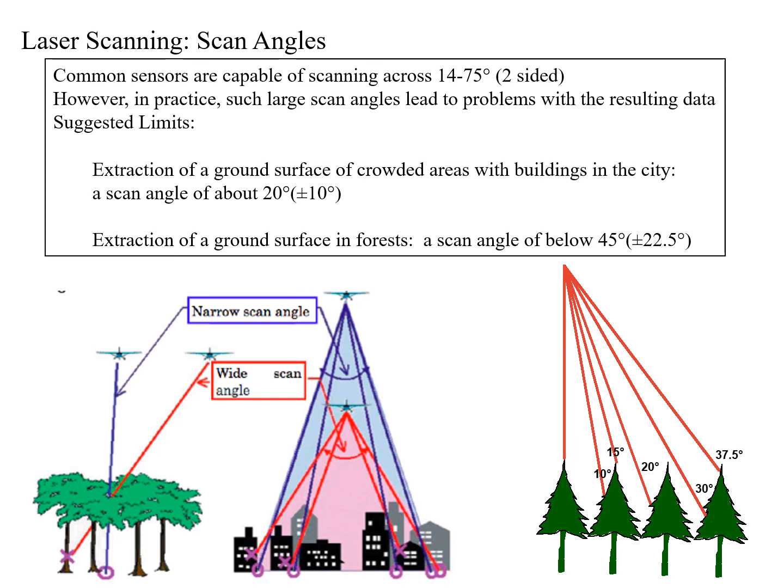It's like displacement. You're no longer hitting the top of the object. You're getting data back from the side. And similar to the distance from nadir, that is a big effect in displacement. The scan angle here is the factor that leads to the most error.